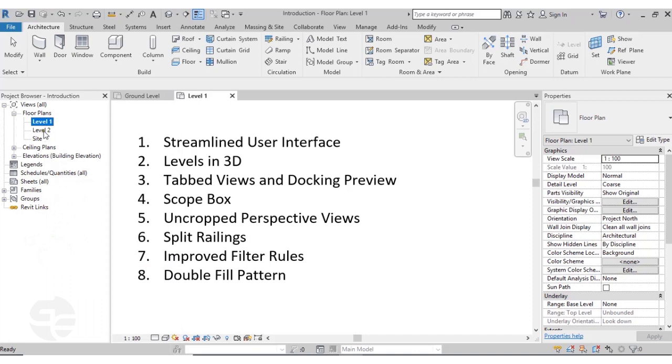You can just select the view here, wait for a while and again click on the view name, where we can just rename our view. I'm just going to rename it as, say, first level. Again I repeat, to rename any view, you can just click on the view, wait for a while, again click on the view and rename it as needed.